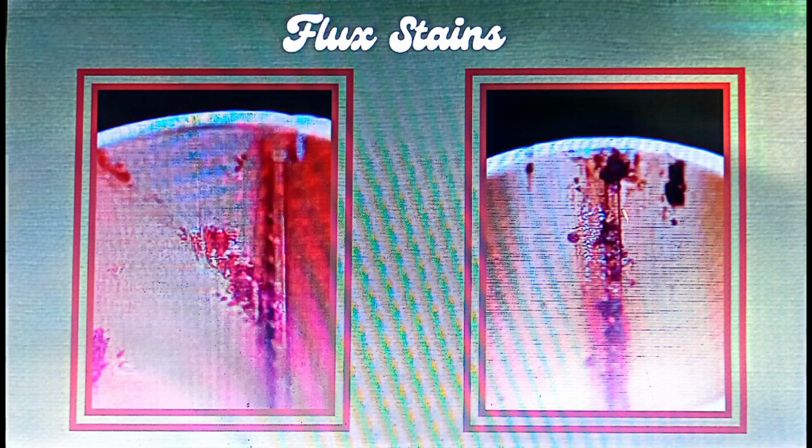Another example would be the flux stains. It belongs to the body manufacturing defects, and it was considered a minor three-piece can defect. Flux stains are described as a dark brown resinous staining on the inside surface of the side seam or lap. The fluxes used to manufacture food cans in Canada are considered non-toxic and will not impart odors or flavors to the product. Common sources of this defect were excessive flux during the side seam or soldering operation.